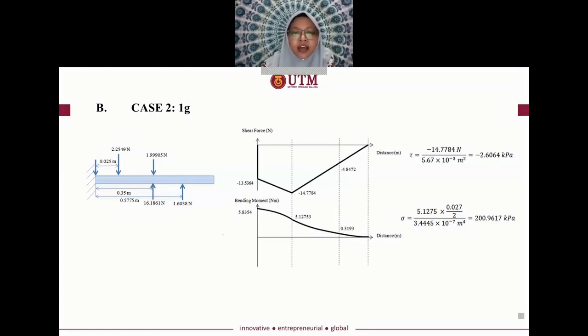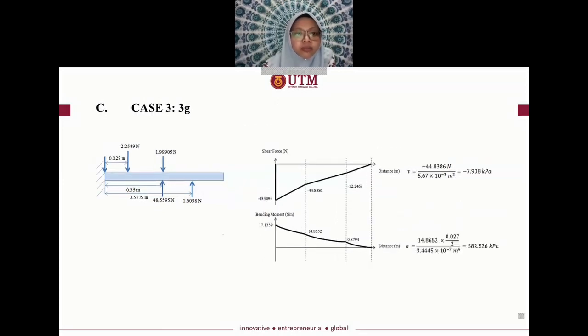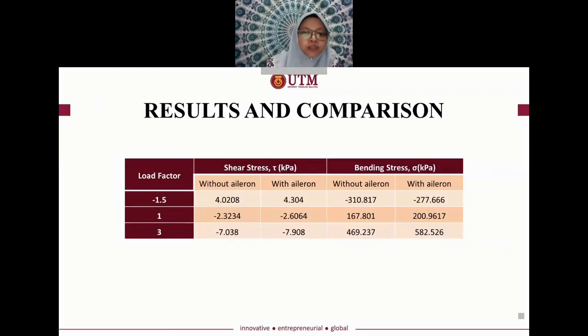200.9617 kilopascal. Finally, for the third case, or the maximum load factor, which is 3G, as illustrated here, the wing should withstand the highest stresses, which are 7.908 kilopascal for shear stress and 582.526 kilopascal for bending stress.